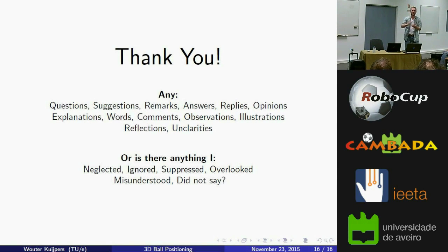Of course, I have to admit, the one in the middle is probably because I positioned the ball incorrectly, that maybe caused that 36 centimeters I was talking about. But the other ones, I think, are caused by the distance from the robot to the projection increasing, so that it becomes a little bit more sensitive to, for example, pixel changes or detections of the ball position projection.